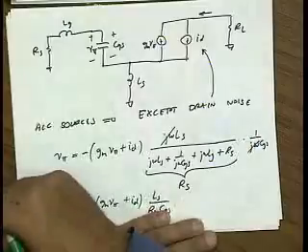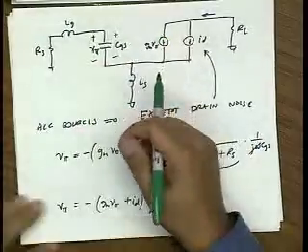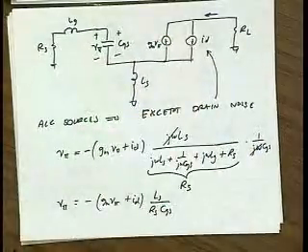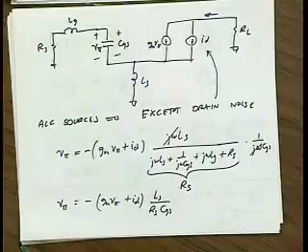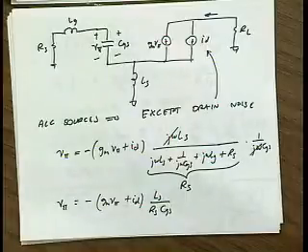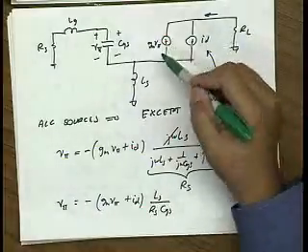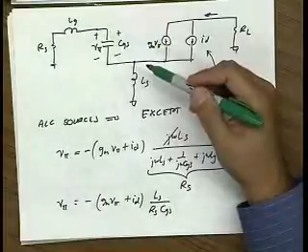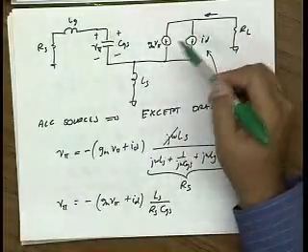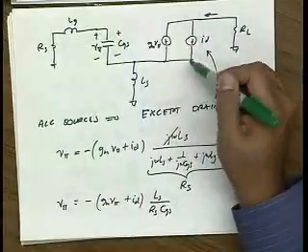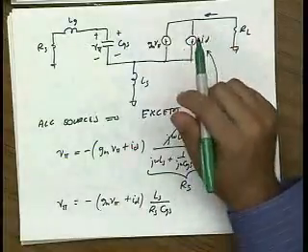Okay. So we're assuming that the noise is white, right? So it takes some finite time for the electron from ID to travel through the gate, and by the time it takes it back, in effect, the current generated should be uncorrelated to what ID is going to be. Yeah, actually, you're right. In a real transistor, the GM has a phase shift. Nothing in nature happens instantly. So there will be a slight decorrelation, and so instead of being 1/4, it's going to be slightly different.